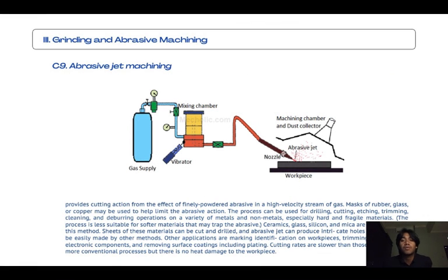In ultrasonic machining we've got a subtopic. The first one is rotary ultrasonic machining, which uses a rotating tool coated with diamond abrasive and ultrasonically vibrated to machine hard and brittle materials. There is no abrasive slurry, but a liquid coolant, usually water, is used. Milling, drilling, and threading operations can be performed, but drilling is the primary application. Non-metals, glass, aluminium, ceramic, quartz, sapphire, and composite materials are normally processed.